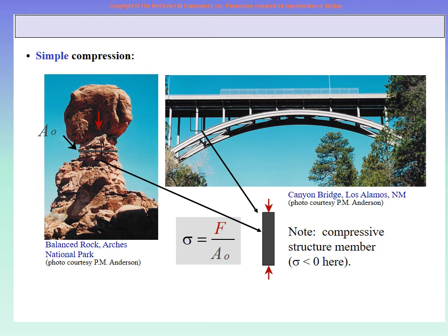But you see, in your earlier math you have done vector mechanics. So if there is a force at an angle, you can divide it into components. So you solve only the tensile load, then you solve only the compressive, then you solve only the shear, and each time you find the x, y, z components of the force. Fx for tension, Fx for compression, Fx for shear, x, y, z components. In the end, you have vector addition, right? Vector addition of x, y, z forces. So you can find the combined load and you can find the combined angle.